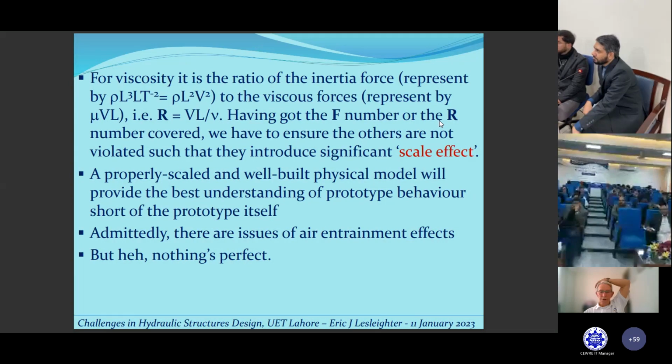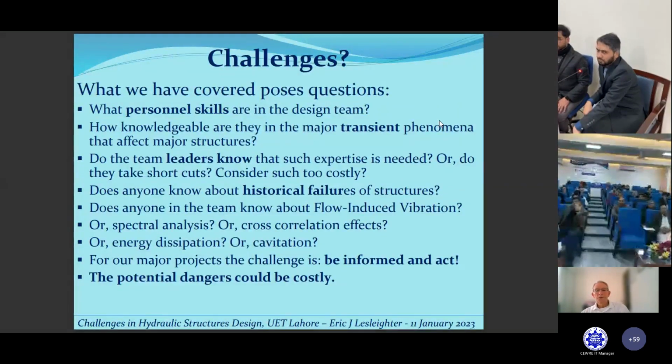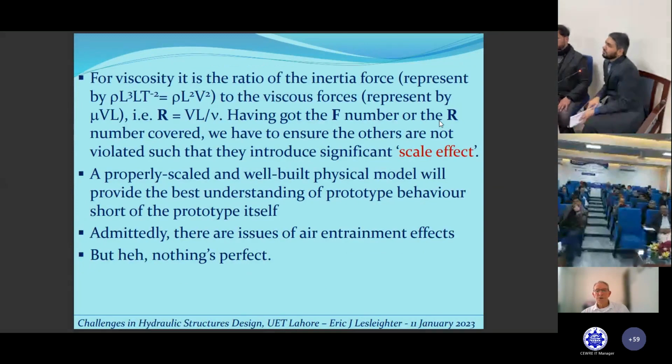I hope you have this slide at the bottom statement here. Gravity is the ratio of the inertia force to the gravitational force. You can digest that one a little later, but that gives us a Froude number. And then at the top here, in the next slide, viscosity is the ratio of the inertia force to the viscous forces, which brings into play the Reynolds number. So you have to have both of those into play when we're looking at these conditions of cavitation and energy dissipation, or more strictly the energy dissipation.